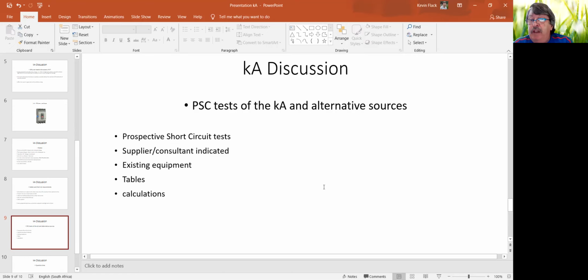There's fairly expensive equipment out there that can check, without causing product damage, what the level of short circuit is. That's done by applying a very short circuit with a defined impedance value, defined resistance, and doing that very quickly and doing the measurement. And of course, as guys doing CFCs, you've got to have the equipment to do that. You need to be able to establish exactly what it is. Other ways of doing it, of course, because some of the test equipment is not available to do 525 or 1000 volt in the mines, for instance.